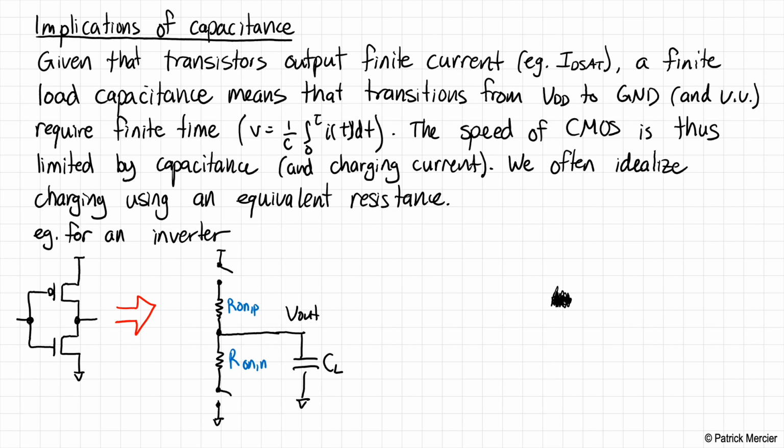Okay, let's just for a moment imagine that this NMOS transistor turns on. Prior to this, the PMOS transistor was on, and so therefore V out had been charged to VDD. And at some instance in time, let's say t equals 0, the NMOS transistor turns on and the PMOS transistor turns off. Okay, so let's just plot what's going to happen to this voltage. I'm plotting V out of t versus t. So we said that at t equals 0, and perhaps for all time before that, V out was equal to VDD because that PMOS transistor was turned on.